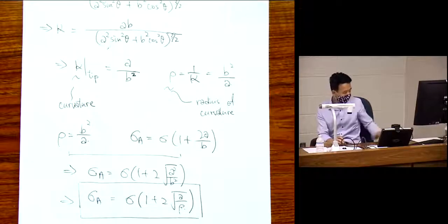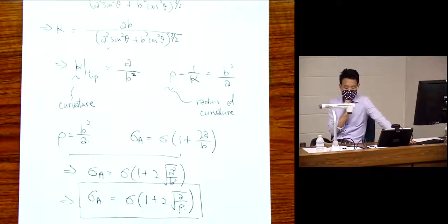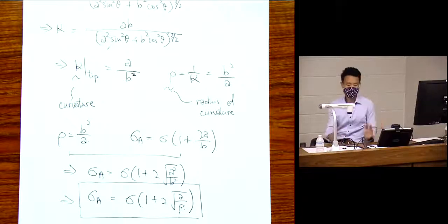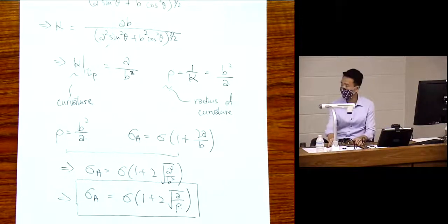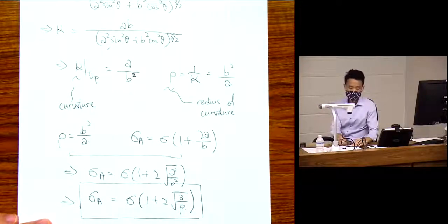But one of the reasons that this is not working is that we have been using a linear elastic solution, right? Inglis uses a linear elastic solution and assumes it to be correct all the way up to the point of fracture. And that is the main limitation, the reason for this infinite stress prediction.